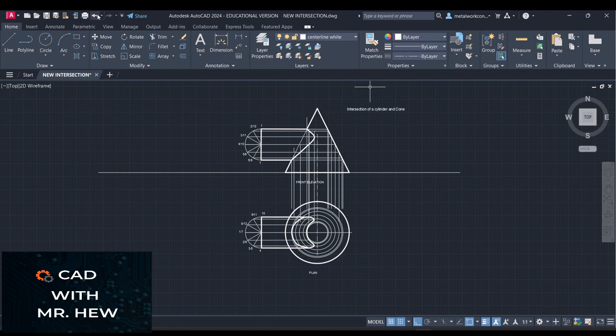So the first thing we're going to do is set out where we're going to draw the 45-degree lines. If you have your T-square and your set square, we draw those vertical lines here. This line will be coming from where the semicircle is.